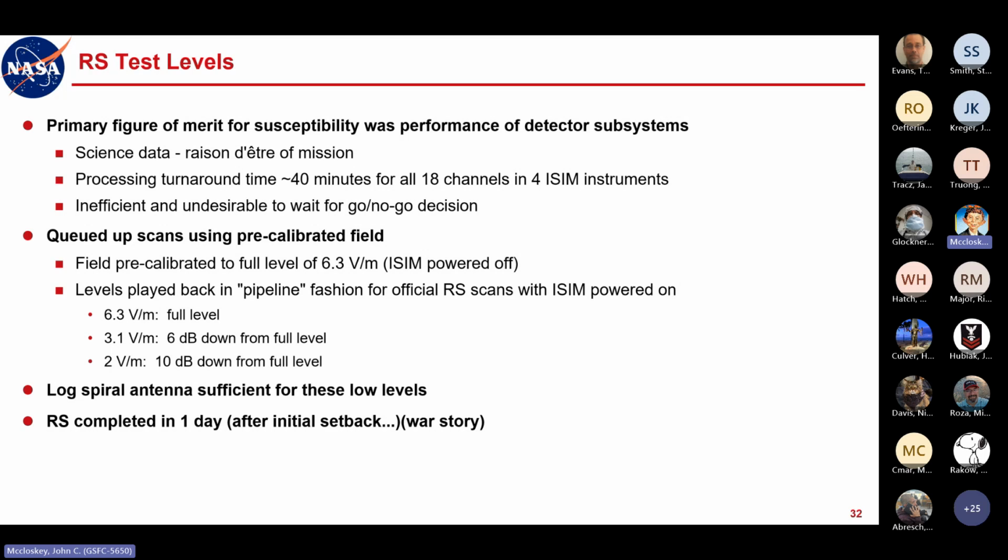But anyway, back to the point, we were initially not seeing susceptibilities where I was pretty much certain that we should. We went through the whole frequency range and didn't see any susceptibility, and something's not right here. Well, it turned out that those new shiny signal generators, the way they were configured, the modulation was not applied internally, even though the front panel was saying your modulation's on.